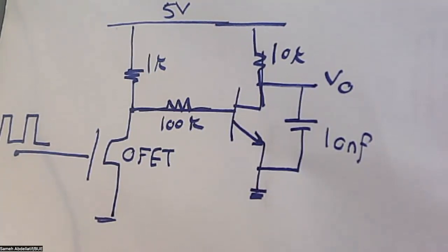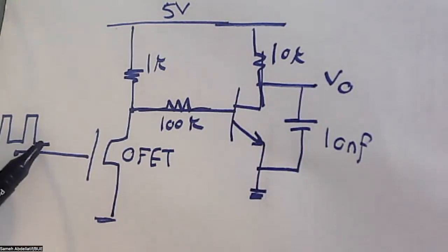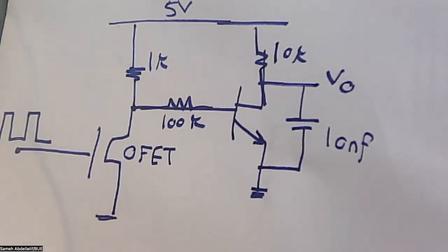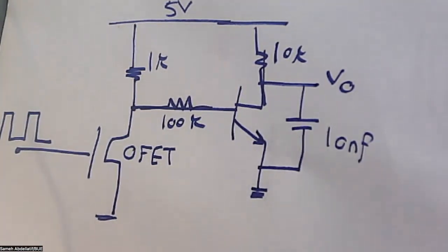Herein, we can use the concept of the field effect transistors in order to apply this process simply by bumping some sort of on-off pulse signal to the gate of your OFET. So whenever you are applying 0 to your OFET, generally speaking, this transistor should turn off, and then your sensor is not working. Once you give it a high signal, then the transistor is turned on and it starts sensing.